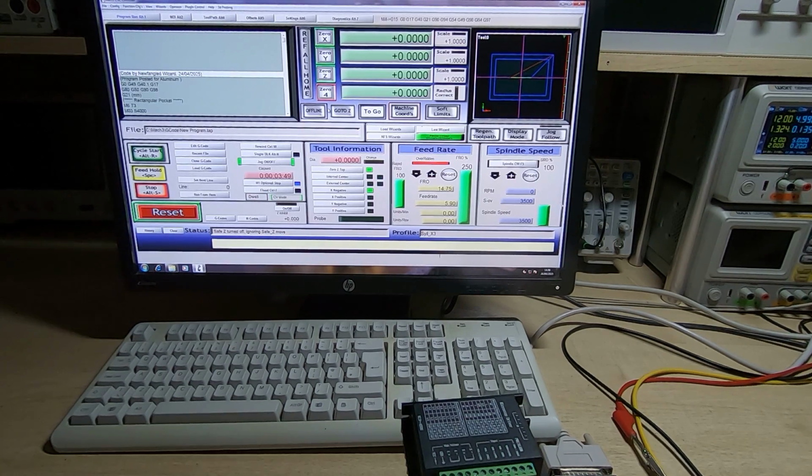But the general way that the tool change works, it's important to understand the general operation and the way MACH3 runs this. Firstly, MACH3 does not hand you total control of the machine. There are other processes going on in the background. So sometimes you write a macro and it would seem like it should do what it wants. It may even work when you step through it, as we'll do in a few minutes, in the editor within MACH3. But then when you try and run it from G-code, it doesn't do what you expect. And that's generally because you've misunderstood what MACH3 is trying to do.